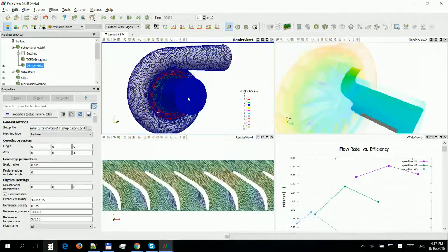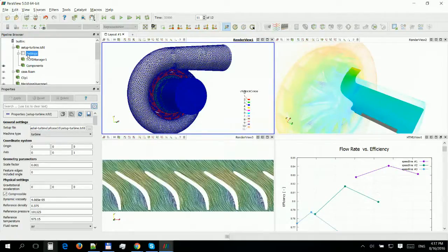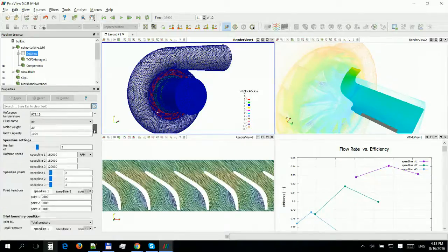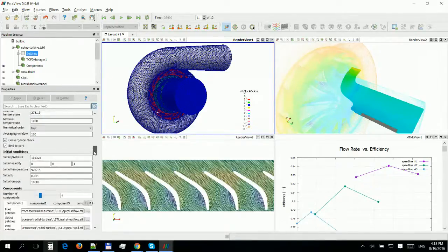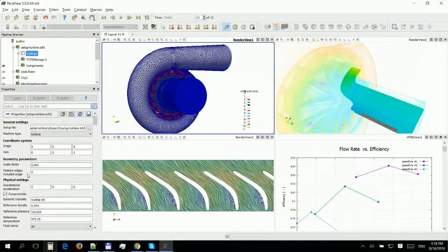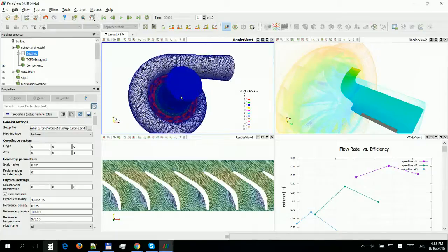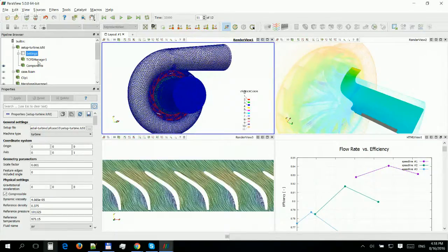And then the other input is the configuration, right? So it's in the settings. You can write everything down here. So you specify here all those parameters of the fluid flow, of like physical settings, geometry parameters, mesh settings, boundary conditions, simulation settings, all of them. So later we can go one by one, but I will try not to go too much in detail. So really, there's the settings, the physical settings, and or the simulation settings. There's the configuration and the surface model. That's the input, right?